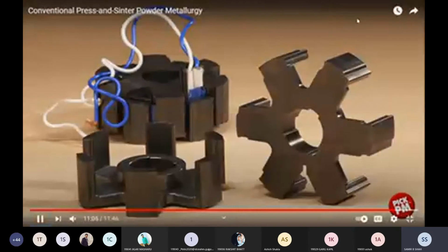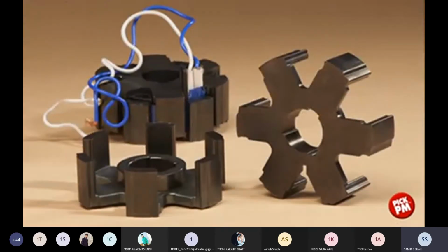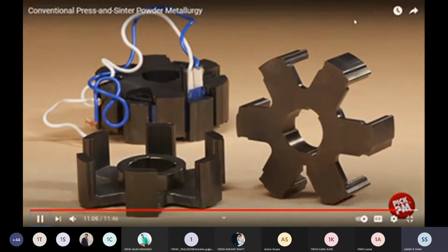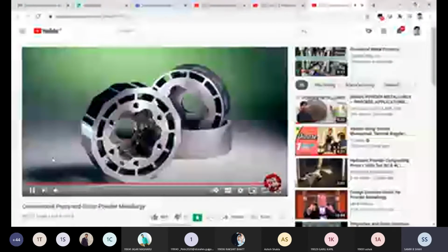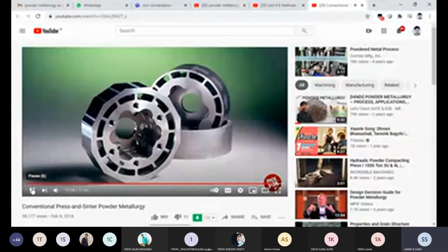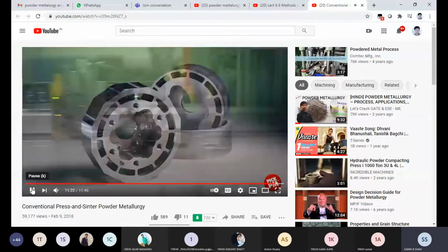Here we see stator cores for electric motors made from soft magnetic composite insulated iron particles. The rotor core for a hybrid electric motor is made from a sintered soft magnetic outer rim and sinter bonded to a copper steel inner hub. Powder metallurgy is a global commercial business and highly studied science. Conventional PM offers cost-effective solutions for high tolerance applications.